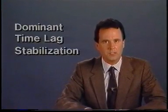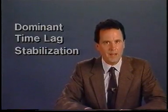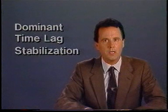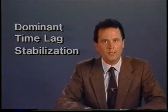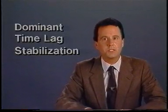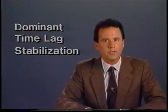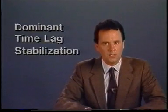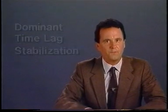This procedure is called dominant time lag stabilization. Simply put, it means that every closed-loop feedback control system is easier to implement and will perform better if there is one dominant time lag in the system. Ideally, this dominant lag would be the process itself. Therefore, all we need to do to achieve dominant time lag stabilization is to select instrumentation that has a response that is much faster than the process.